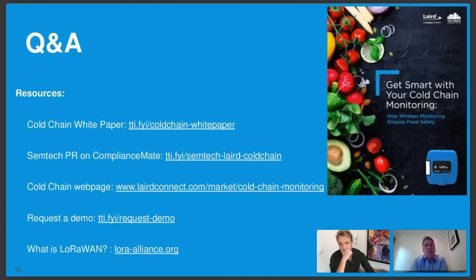The average number of sensors is roughly around 6. So most implementations we've seen, 1 gateway and 6 sensors is about the average to cover that environment. But one of the nice things with LoRaWAN is that if you do need more range, to cover additional areas, you can literally just drop in another gateway to service that area and increase your scope.